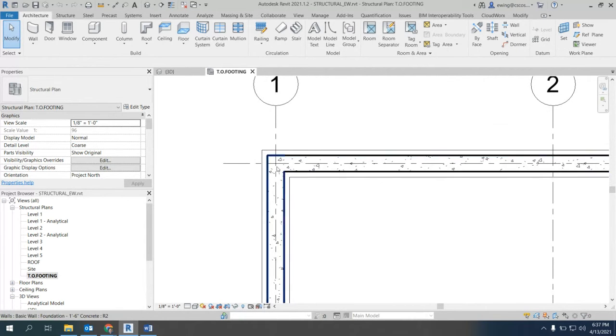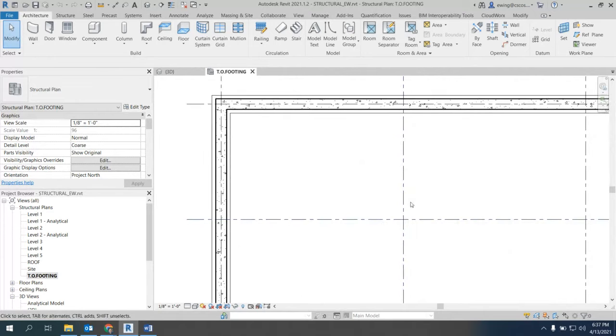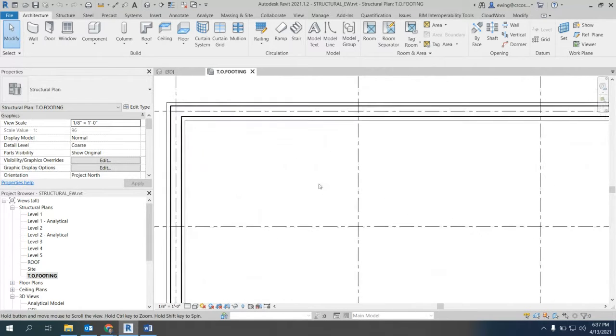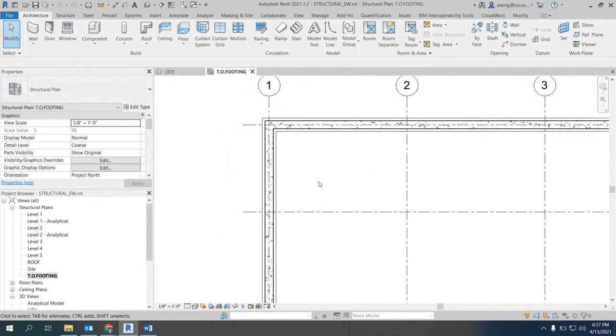So we need to put in pilasters for the columns that are going to be on the exterior, and we need to put in piers for the columns that are going to be freestanding. The difference being a pilaster is a foundation that is poured into another foundation monolithically, whereas a pier is freestanding. You can picture a pier that goes out into the ocean, right? The same kind of idea.